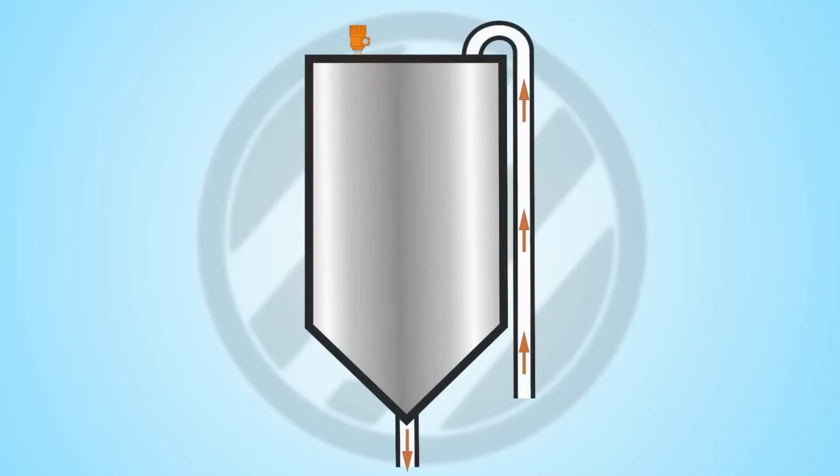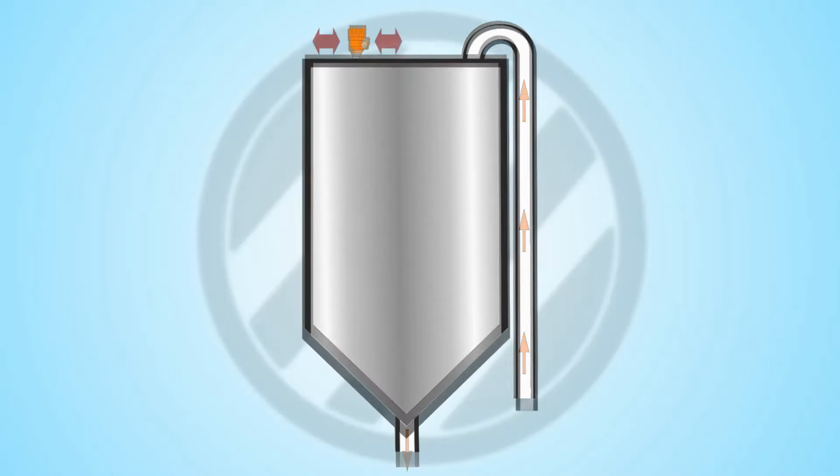Firstly, we need to note key information about the silo. We need to know where the silo is filled from. This will be via a fill pipe to the top part of the vessel. We also need to know where the draw-off point is. The level transmitter must be mounted away from the fill pipe to avoid false readings. The recommended position is about 1/2 to 1/3 radius.